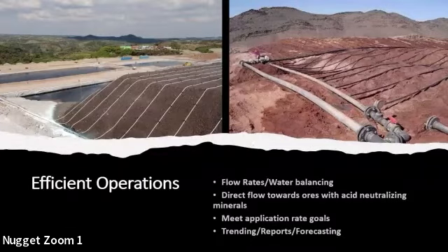And at 0.5, we get down to 8-9 meters depth, which was the depth of concern of potential dynamic liquefaction. So in summary, for the liquefaction analysis in the heap, there is a record of liquefaction down to 15 to 25 meters within the heap.